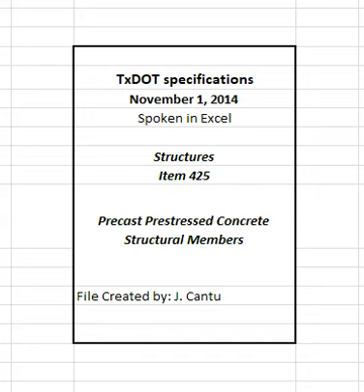Immediately replace damaged packaging or forms, or restore them to original condition. Have the shipping package or form clearly marked with the corrosion inhibitor type, packaging date, and a statement that the package contains high-strength prestressing steel. Handle prestressing steel carefully to avoid abrading, nicking, or kinking the strand, bar, or wire. Protect prestressing steel from damage and corrosion by storing it above the ground on platforms, skids, or other approved supports. Any pitting or tightly adhering rust on prestressing steel will be cause for rejection of the steel.